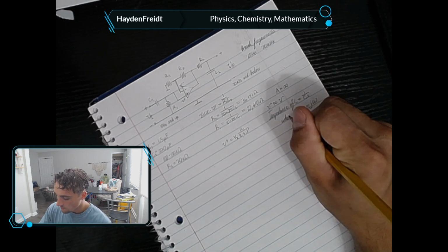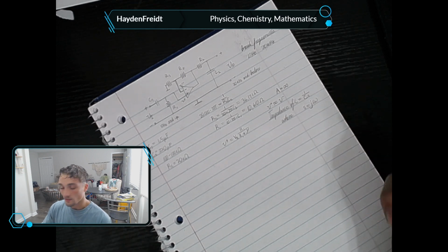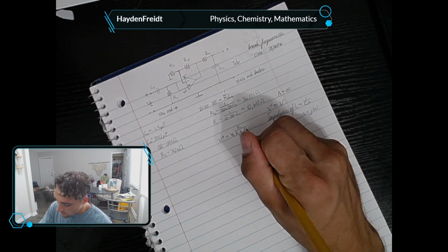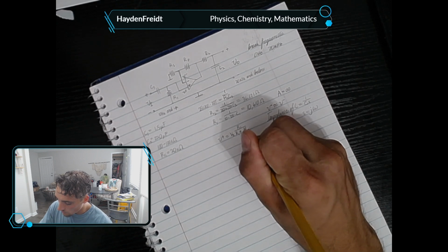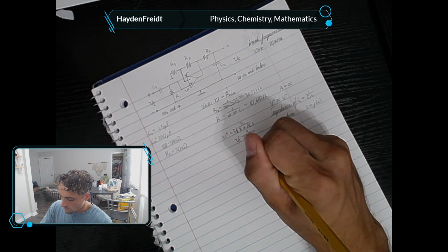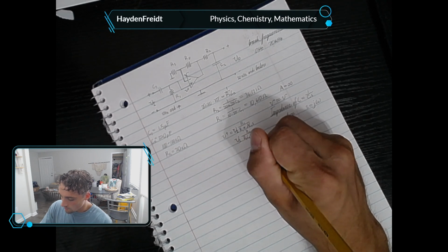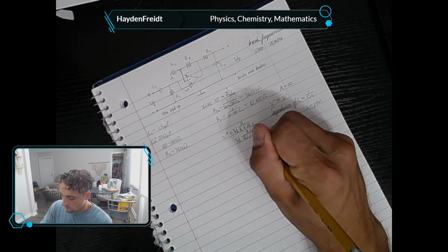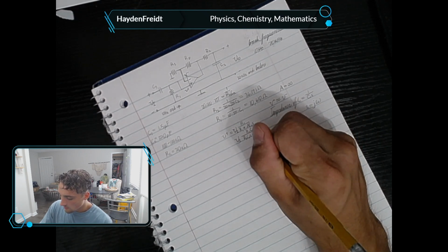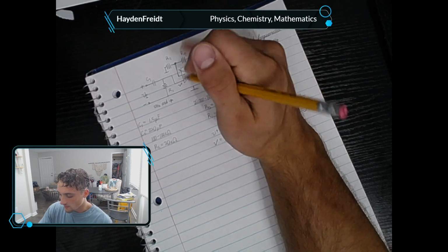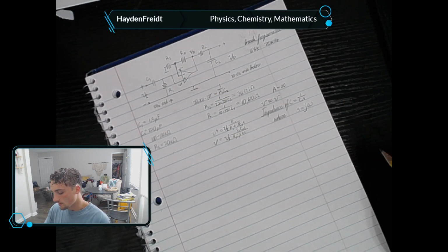Where S equals the imaginary number times omega. So it's going to be R1 over R1 plus 1 over C1 S. That's going to go into the numerator. For the node, we're going to call it Vx. We're just going to give the node some sort of variable.